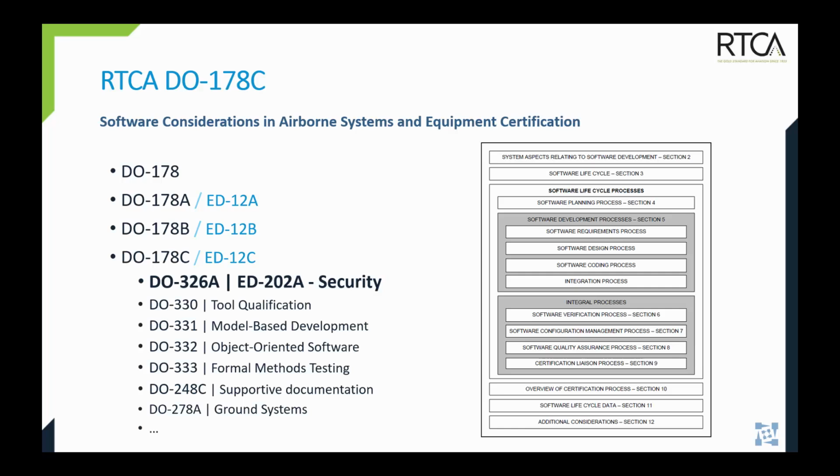the US and around the world, such as the EuroCAE working group, to help develop this comprehensive and contemporary aviation standard. The original DO-178 standard was released back in 1982. However, it was considered not very useful, then quickly followed revision DO-178A, published in 1985. This revision focused more on modern software engineering principles, verification practices, and introduced a correlation between critical failure conditions, level numbers 1, 2, and 3, level 1 being the strictest. You may know it better today as Development Assurance Level, or DAL.